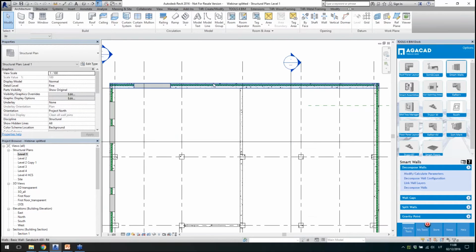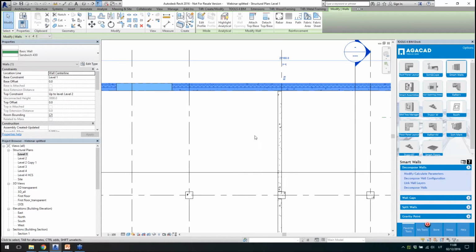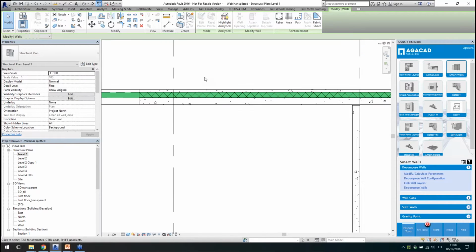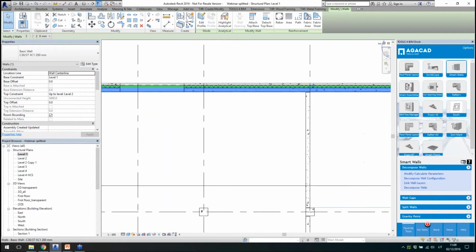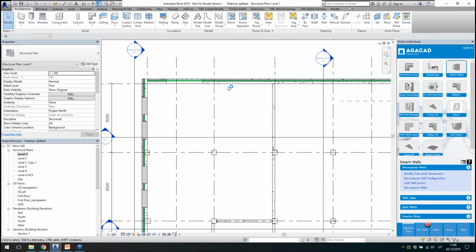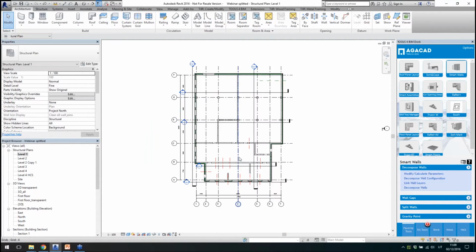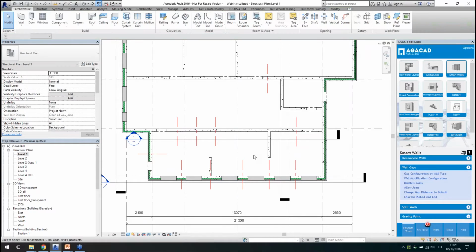So this is first of all, and then you can divide, let's say, one multi-layered wall into different walls. So if I do this command, it will create 3 walls instead of the one. Sometimes in situations when we have an architectural model and we want to separate architectural layers from the structural layers, we can use this command and just hide unnecessary layers and start our work. So it depends on the things you want to create. This option is available, and then most of the features I want to show and concentrate on is splitting of the walls.